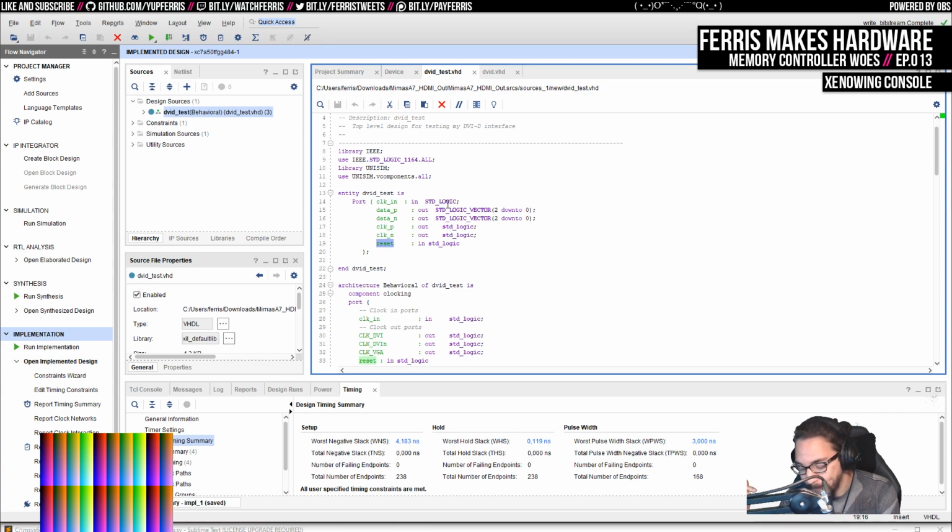So getting set up with that and making sure that I can still read and write over the UART while still having the board be programmable is going to be interesting. Because my guess is that the FTDI chip on this board that does the UART to USB conversion is a lot more advanced than the one that was on my other board. And on this board, it's also hooked up so that that's the way you program the device, unless you have an external JTAG cable.